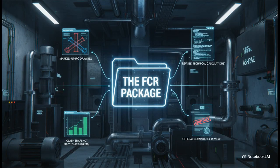You'll need a marked-up drawing showing the before and the proposed after. A crystal-clear screenshot of the clash, maybe from Revit or Navisworks, is a must. You've got to summarize how this change impacts materials and costs. And this is critical. You have to include your revised technical calculations and that formal compliance review.